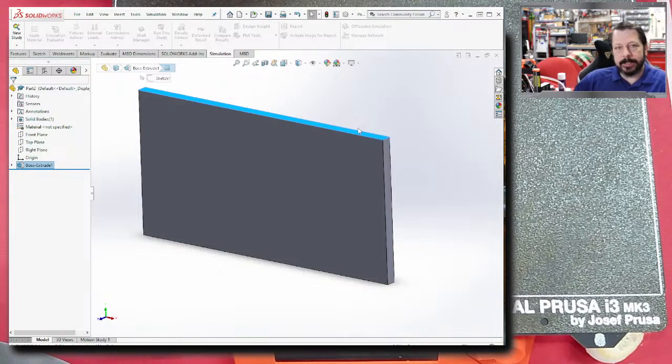This process is assuming that you're going to print this in a metal, or maybe a nylon, one of the laser type printers, an SLA printer, where it's going to be solid everywhere. It doesn't have a hollow interior. It's solid, and the material is much less layer dependent, like the shear between the layers being the weakest part. It's assuming you're using one of those SLA or laser sintering of metal type processes to produce the part, not FDM printing.